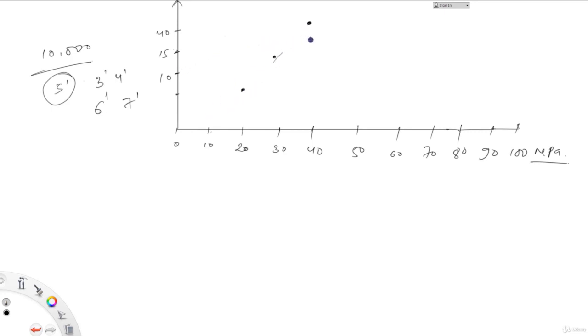Okay. And same thing will happen. So there will be concrete cubes where the mix happened very well, and the concrete was also rich, and due to this reason they will get certain higher strength than the 40. So let's say that 15 got 50 MPa, let's say that 10 got 60 MPa. Okay, so if you join these points, you will get this kind of curve, and this we call as the, okay, so this should be here. So this we call as the bell-shaped curve, and this distribution we call as the normal distribution.